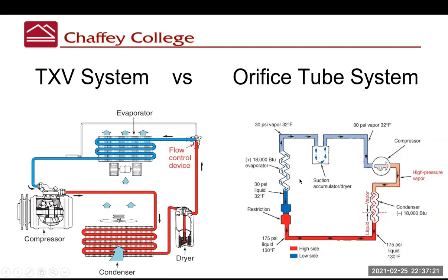Again, your refrigerator works the same way. If you pull out your refrigerator and look at the back, you might see some coils on the back of the refrigerator. Well, that's your condenser. That's where it releases its heat. You can hear the compressor running inside your refrigerator. Underneath, somewhere inside the refrigerator, there's an evaporator. They take the air that's inside the refrigerator, they blow it across the evaporator, and it cools the air and keeps the inside of the refrigerator cold. And somewhere there's a flow control device after the condenser and before that evaporator. So that's how your refrigerator works at home.